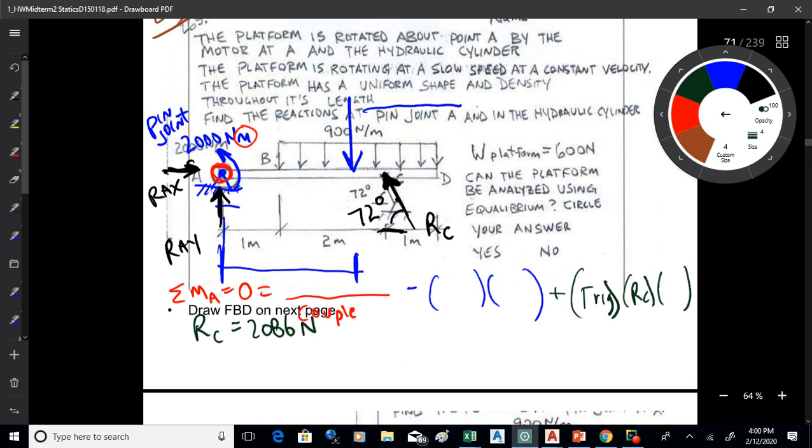All right, now once I have that, what I like to do, or I use moment equations usually as the first one. That's the normal pattern. But moment equations are more complex than force equations. So the next thing I would probably do is run force equations because they're simpler. They take less time. I'm less prone to make error, et cetera. So if I can go with force equations, I just go ahead and do that.